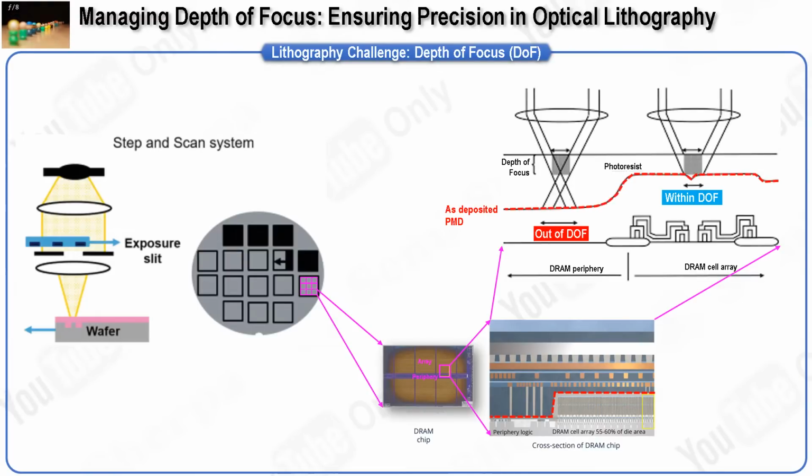Depth of focus refers to the challenge of achieving accurate patterns of the desired size and shape during the lithography process. To illustrate this, consider the scenario depicted in this slide. In this slide, the top left diagram illustrates the step and scan system used in lithography, where an exposure slit moves across the wafer surface to project the pattern.